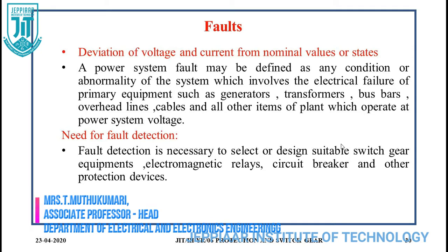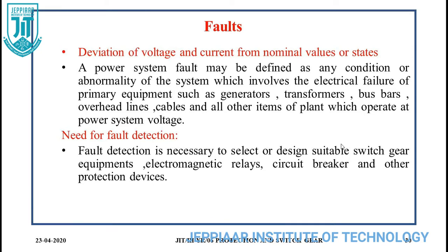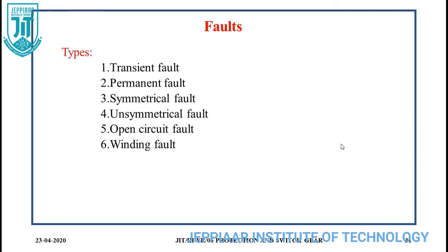And what is the need for fault detection actually? Fault detection is necessary to select or design suitable switchgear equipment such as electromagnetic relays or circuit breakers and other protection devices. Once you know the type of fault, then only can we choose the power system protection devices.